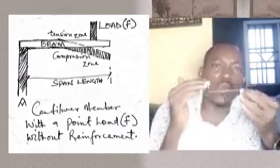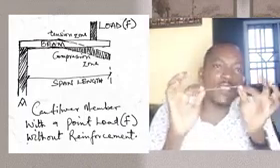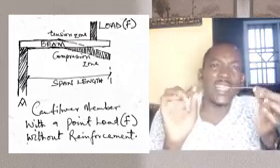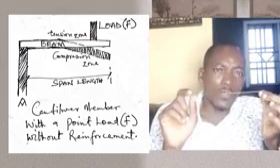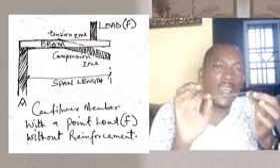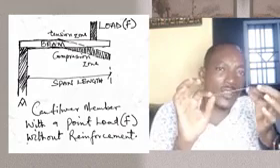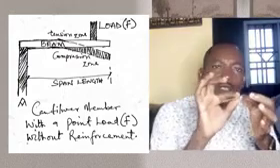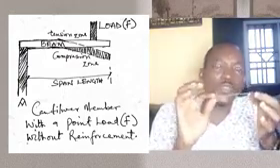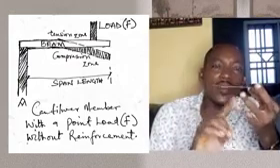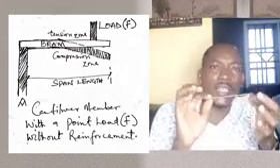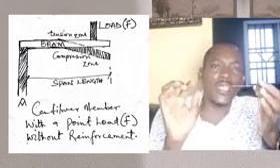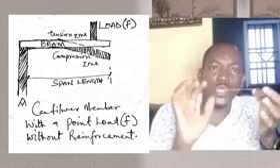Now you are able to identify that once we have this kind of connection, the top area is our major point of focus. That is the area where we need to place our rods. Now the amount of rod and the size of rod that you are going to use here is gotten theoretically. If it's going to be Y12, Y16, Y20, and so on and so forth, that will be determined through calculation. But the basic thing I want to get here is where you position your rod.